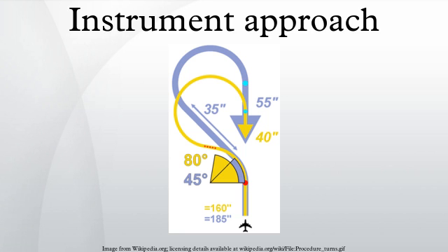Pilots should be aware that there are significant differences in obstacle clearance criteria between procedures designed in accordance with ICAO PANS-OPS and US TERPS. This is especially true in respect of circling approaches, where the assumed radius of turn and minimum obstacle clearance are markedly different. Rate of descent formula: a useful formula pilots use to calculate descent rates.